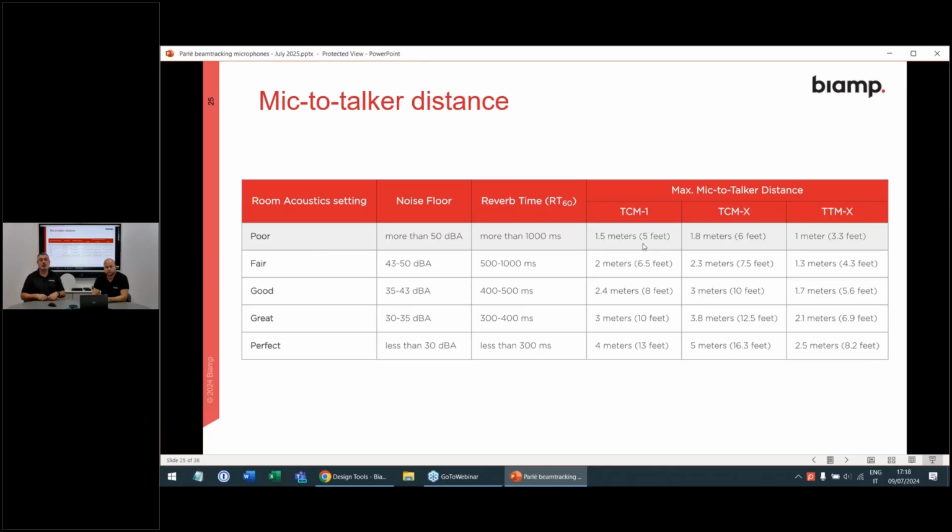And so we need to use the advantage of the pendant. The advantage of the pendant is, thanks to the cable, we can go down and go closer to the participant. In that way, we can reduce the distance and get a very good result. And the last is the table microphone. In that case, using the table microphone, we are able to reduce the distance between the microphone and the participant even further. Like in this case, I'm less than 40 centimeters from the microphone.